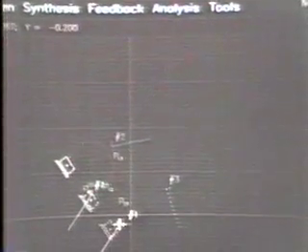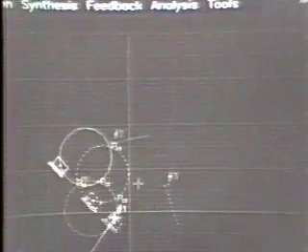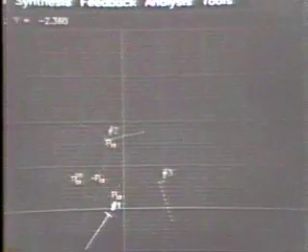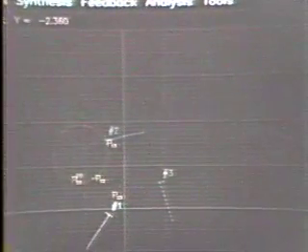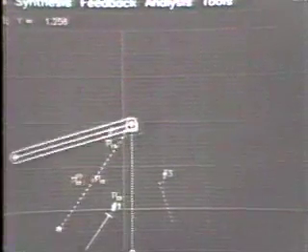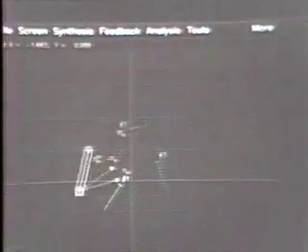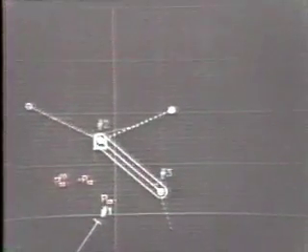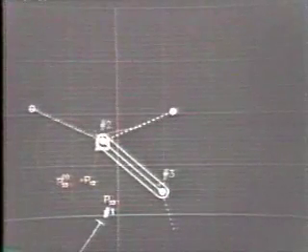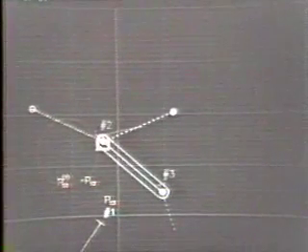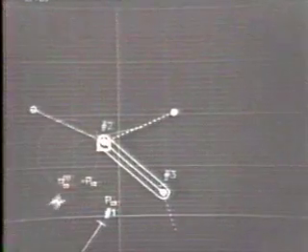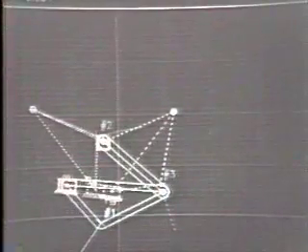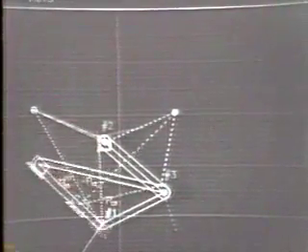The designer can grab the slider symbol and move it around to any location on those circular loci. The slider is shown not only in the number 1 reference position, but it's shown dotted in the 2nd and 3rd positions as well. Having picked a tentative slider, the designer is now picking a crank link for the driver for this slider crank mechanism.